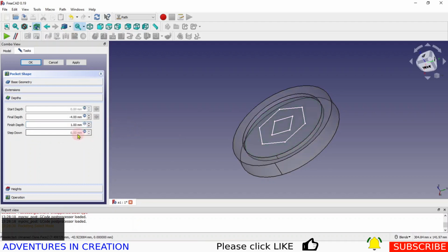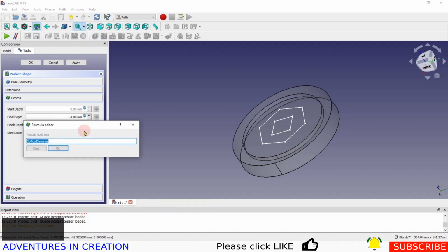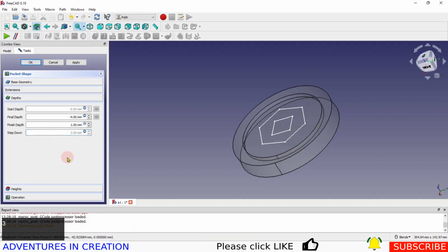So we want that. And by default, it picks a step down the diameter of your cutter. Well, A, I don't like that, and B, I'm only going 4 mil deep, so I'm going to pick 3 mil. So we're going to start at depth 0, which is here, and it's going to work its way down to this depth, which is here, and it's going to do that with a 3 mil step down.